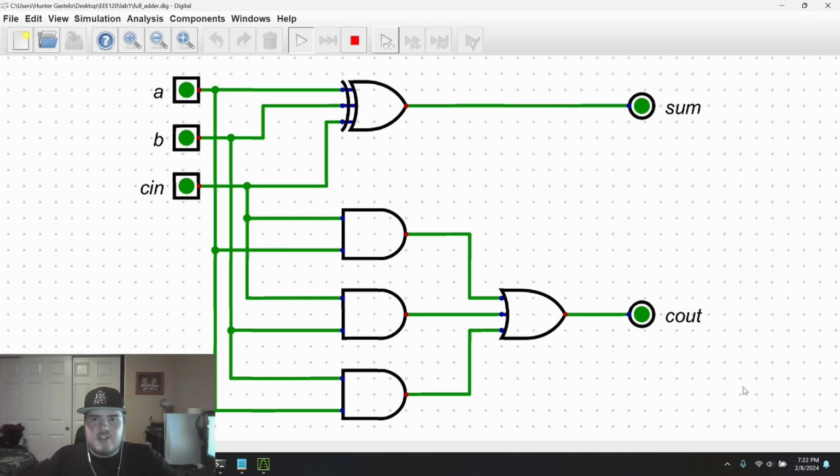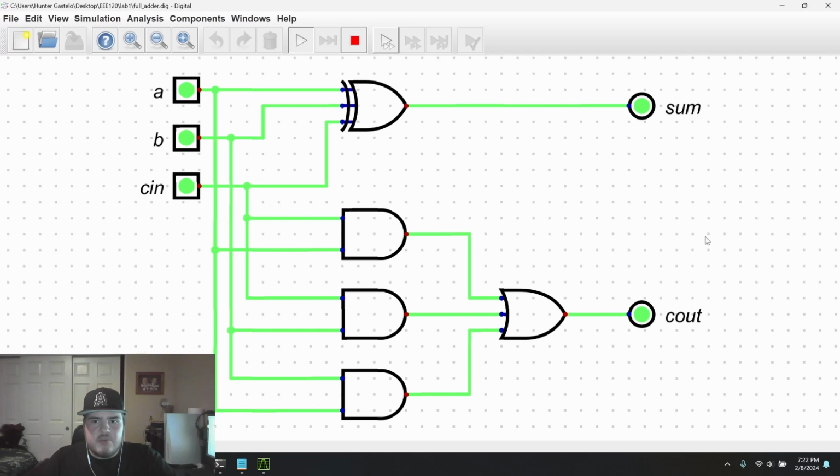And this is also like a 2-bit binary output, like the half adder, in which we see binary addition. 1 plus 1 is going to equal 2, and 1 plus 1 plus 1 is equal to 3, in which the sum stays in the binary digit place where this full adder is, and Cout will be carried to the next place. And I'll bring up the waveform for this one next.